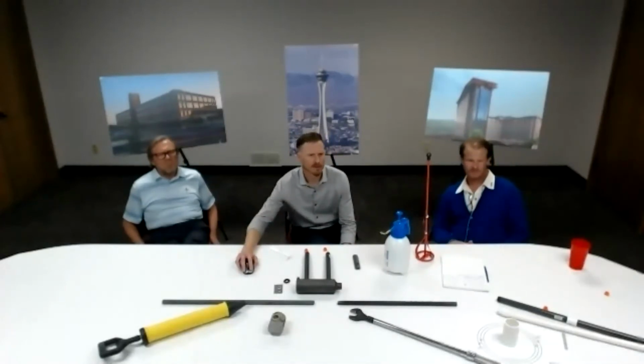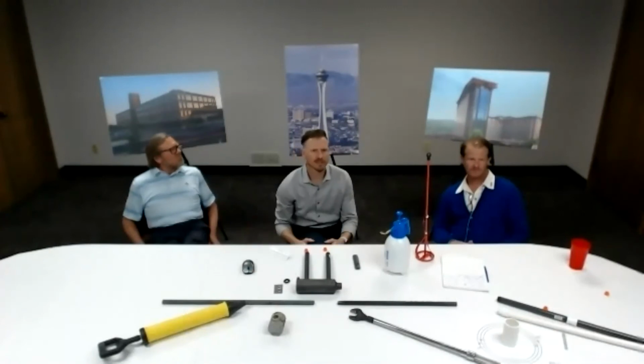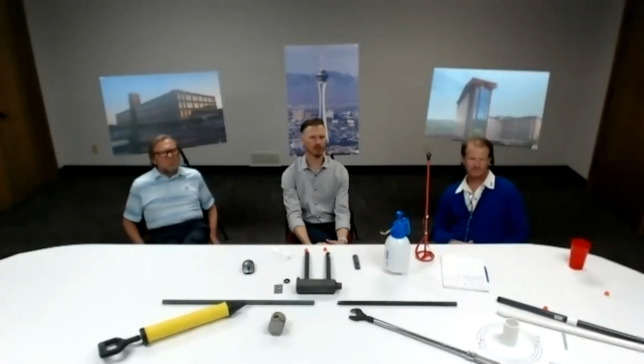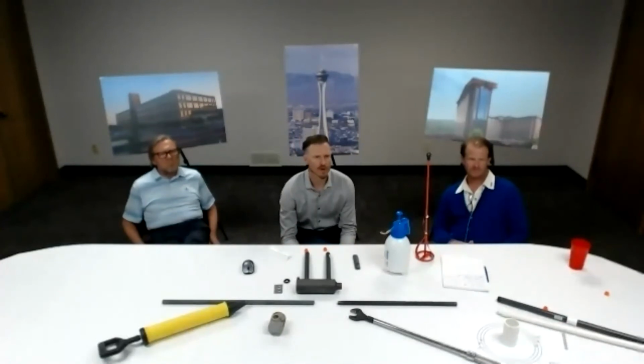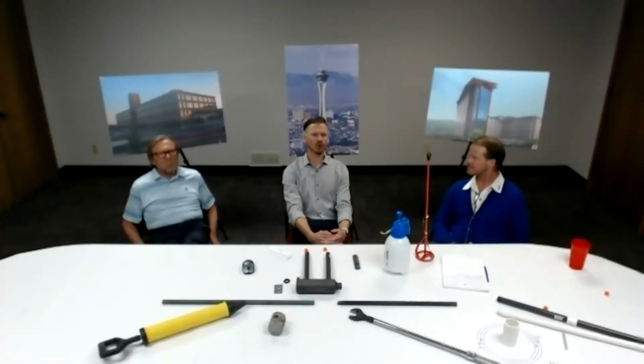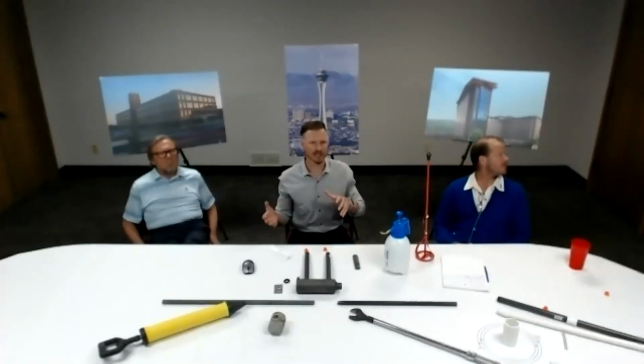Let's see here. There was a question. You mentioned the shear transfer during construction, that reshoring may be required at the joint. In your projects where you design for third span cantilever to support the other slab and no reshoring is used, are there any mechanical attachments? So the question being answered is, when the cantilever slab has been designed to support the slab coming from the other side, is there anything else you need, or shear keys you recommend?